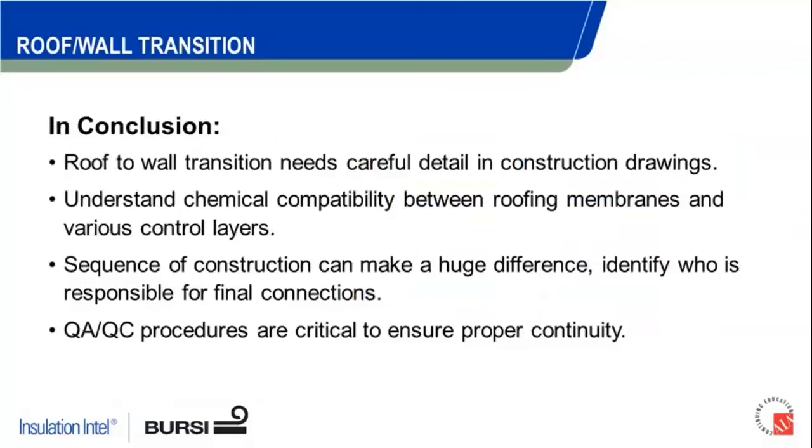In conclusion, at least from a transition standpoint: careful detailing and construction, and really, back to the idea of coordination, understanding where one trade's ending and where the next trade's picking up is really crucial, along with the compatibility of various membranes as we're changing from one system to the next. Again, the sequence of construction, the third bullet down: who's responsible for the final connections. And that's pretty much the transition.